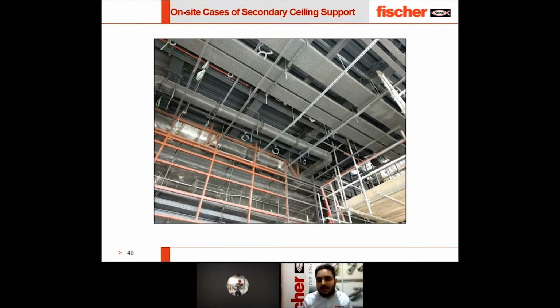Mustafa, is the system designed for lateral deflection? Lateral deflection, yes. In the false ceiling system, we consider the lateral expansion and thermal expansion, so we consider that also in our study. What's your maximum drop from slab height to ceiling? For the threaded rod, it's 2.4 meter. If you use two threaded rods, you connect them with the channel. Each threaded rod is 2.4, so it's okay. The important thing is that it must not be continuous for more than 2.4 meters as per the code.